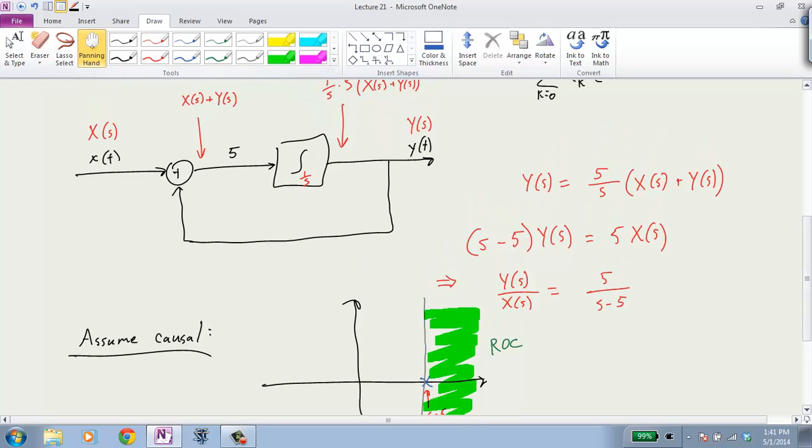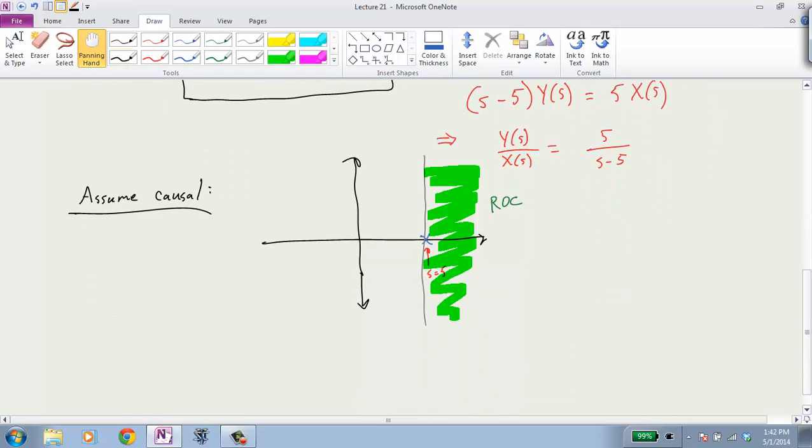Well, looking at this system without doing any Laplace transforms, you should have known it was unstable. If you think about what's going to happen, put a little bit of an input in. This integrates the input and then gives positive feedback. In other words, it adds the integral back over to the input. So you can imagine that this is going to keep accumulating more and more, get bigger and bigger. And let's calculate exactly what the impulse response is, because we have the Laplace transform right here.